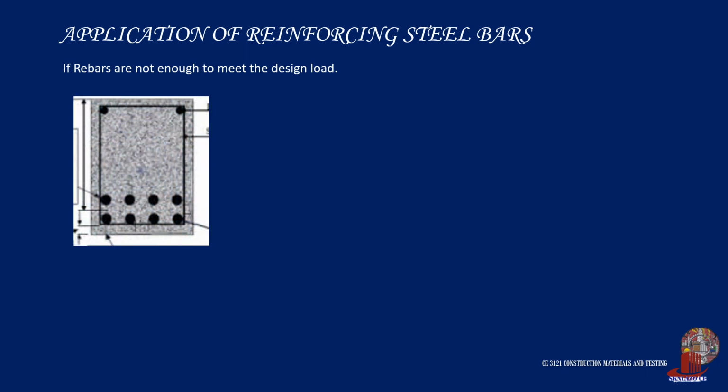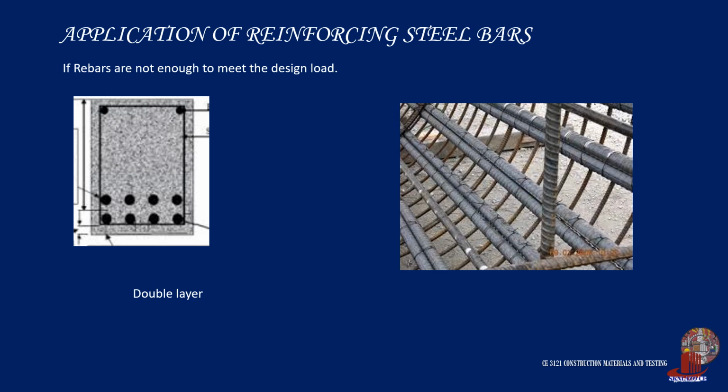In design, as one would have to meet the requirements imposed by the load, economics would still be considered, thus design would start from the smallest possible diameter. But if the rebar isn't enough, say we already exhausted D36, yet the design load still requires more, multi-layering is a possibility, especially for beams, or the other would be bundling of bars. Such methods would be further discussed in design subjects.